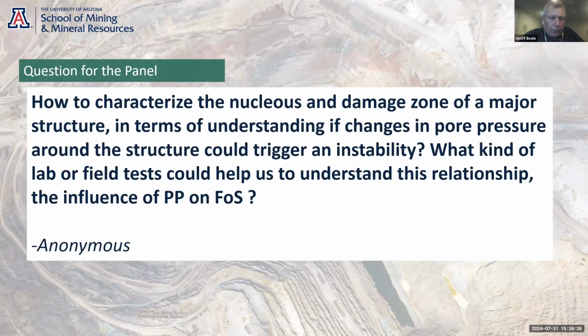and does that situation change, and could that structure then start to form part of the active flow system and create more issues. But I think the answer to the question is piezometers, and I'll let somebody else have a go at it. I was just going to follow up on that, Jeff. One of the most important things to remember on this concept is that the hydrogeological data overrides the geologic characterization.